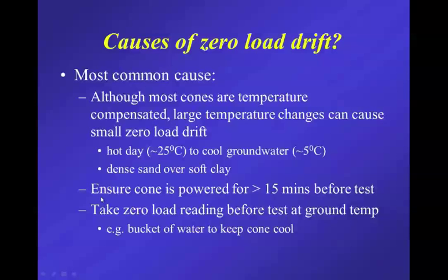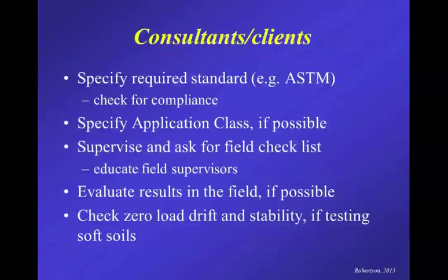Ways to overcome this, ensure that you've powered up the cone before you start the test, before you take the initial zero load readings, and also try and keep the cone at a temperature similar to the ground and groundwater. So if you're in an environment where the groundwater is quite cool, then sometimes keeping the cone in a bucket of water helps keep the temperature closer to the ground. And so when you take the zero load reading, the cone is already close to that correct temperature.